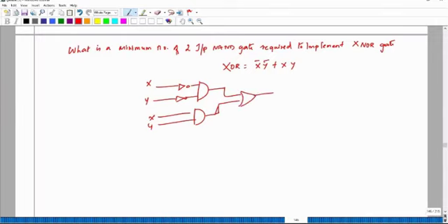So I already told you for AND gate, for the output you have to add 2 NOT gates. For OR gate you have to add 2 NOT gates at the input. Okay. So first let me add 2 NOT gates at the output of the AND gate.